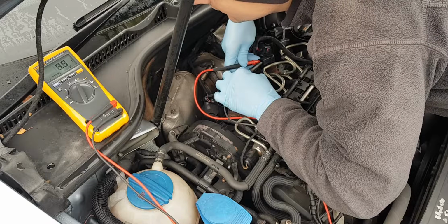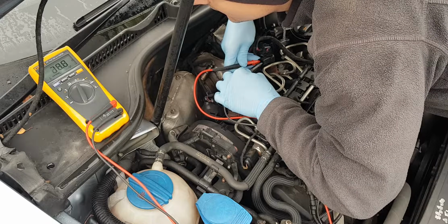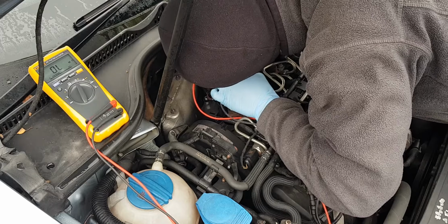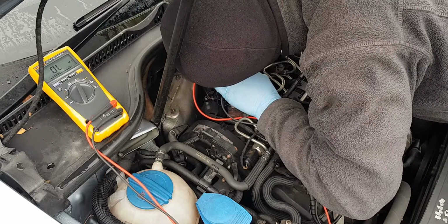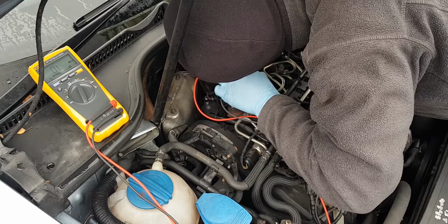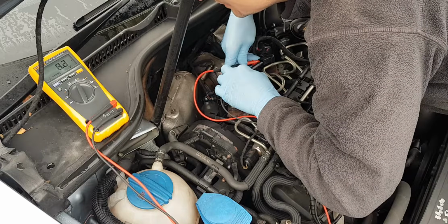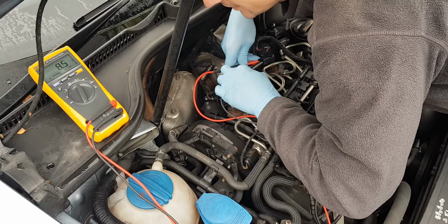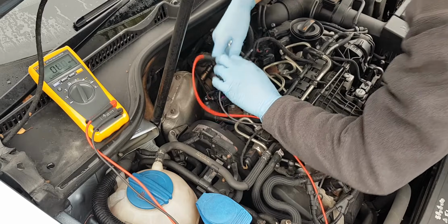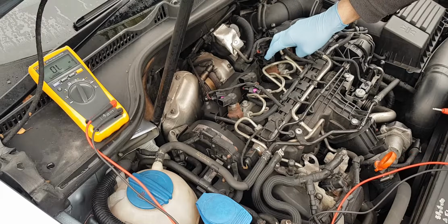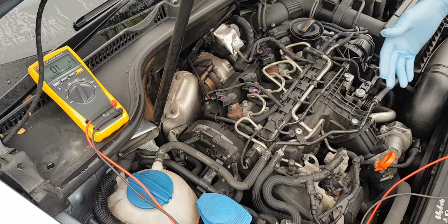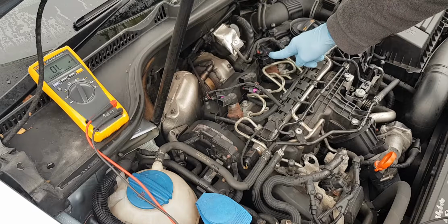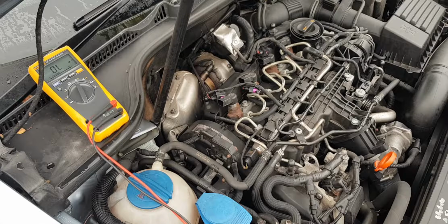So it's showing a difference. Put this properly here. I'm getting about 8.6 ohms. So clearly a big difference, and possibly the coil in this injector is gone, though I'm not 99.9% sure. So this is our problem, a bad injector. Please stay tuned, and I hope I help somebody else with the same problem.